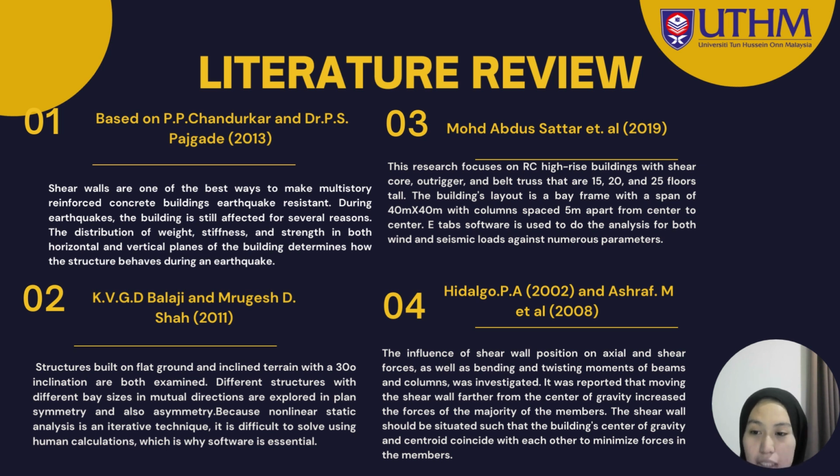It was reported that moving the shear wall further from the center of gravity increased the forces of the majority of the members. The shear wall should be situated such that the building's center of gravity and centroids coincide with each other to minimize forces in the members.